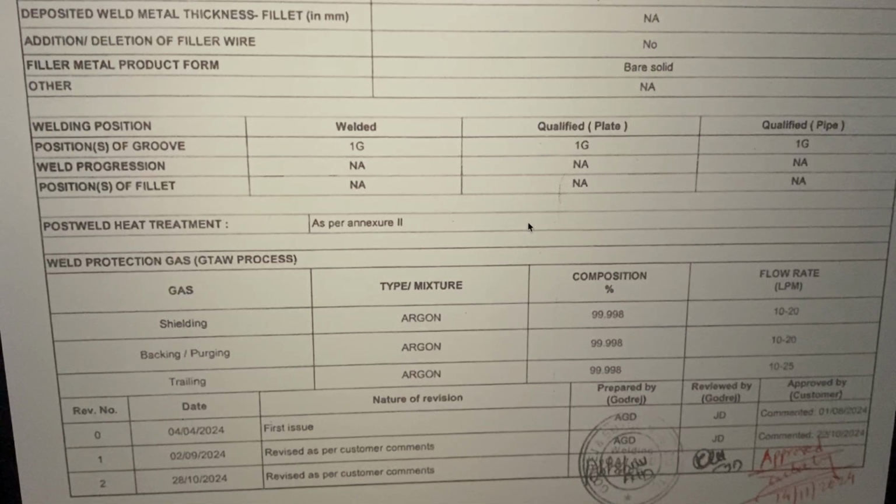Are we going to use a pre-mixed gas? Are we going to have our own mixer? How are we testing the pre-mixed gas, or how are we testing the gas which we are going to mix with our mixers? And then are we going to use any backup purging from the other side of the welding, and on the front side also, are we going to give any extra shielding? Are we going to do the welding in a glove box or that kind of atmosphere?